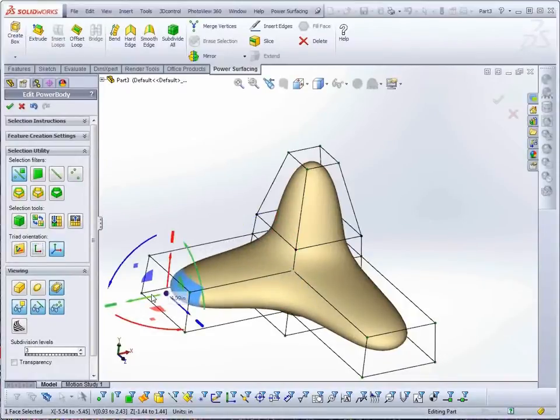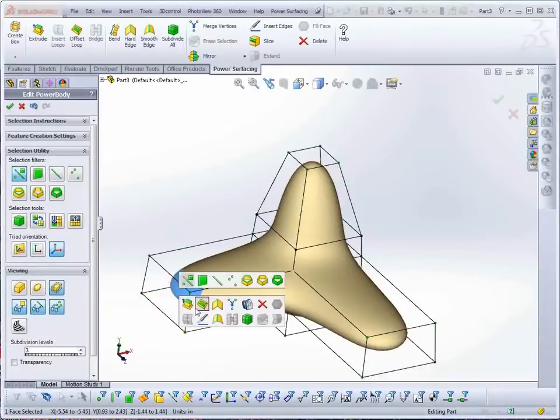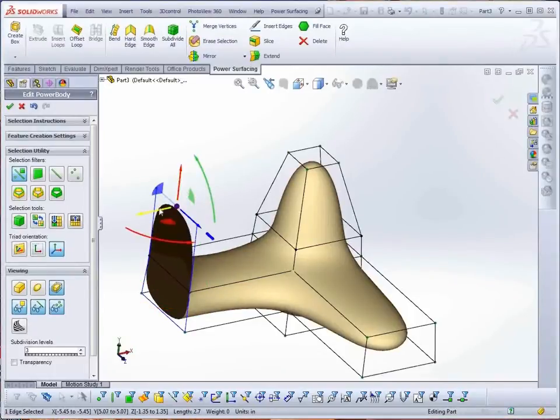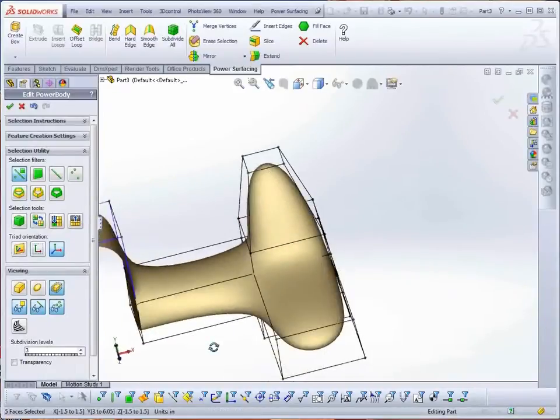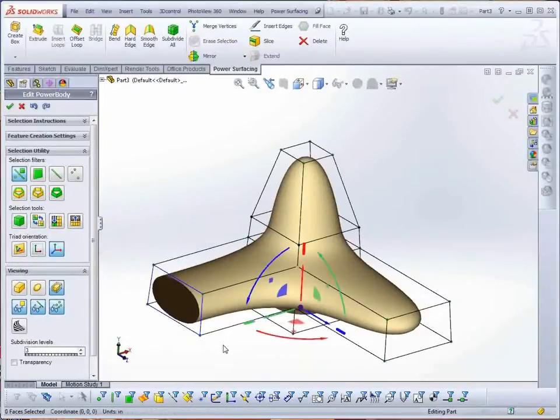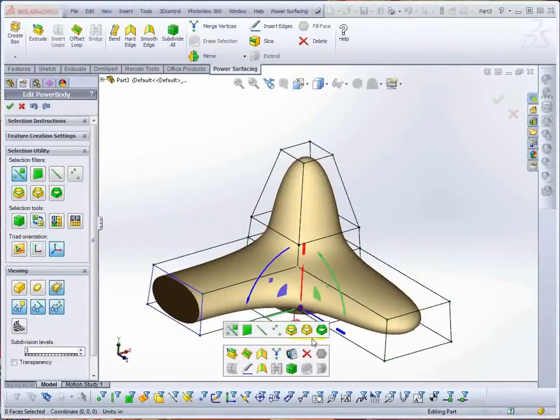The quick extrude also works on open edges, so if you are used to modeling with surfaces rather than volumes, you will probably find it quite useful. I'll delete a face to give me some open edges. Then select one of them and extend it by holding the A key down as I use the triad to move it. I'll do a few undos, and then cap it back up with the fill face from the right-click menu or from the toolbar.